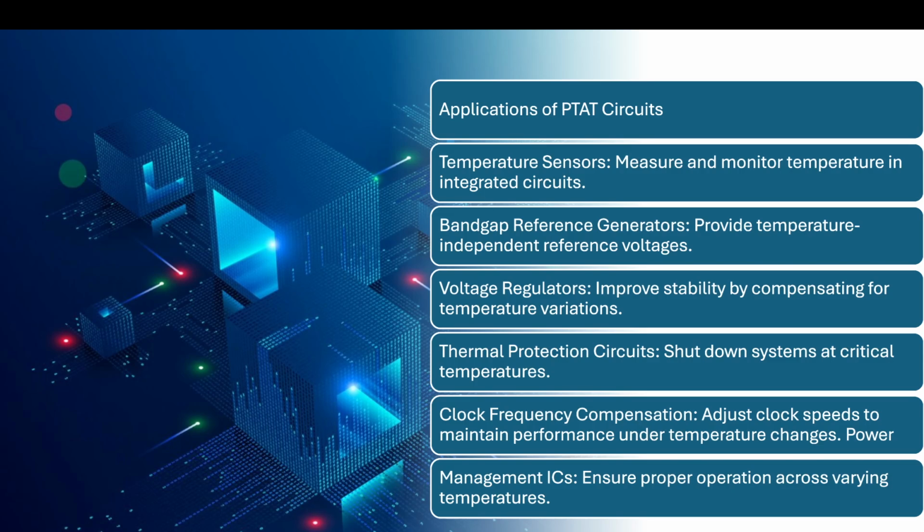These are some applications, and mainly where you design a chip, in most parts of your chip area you can provide this circuit and check whether your temperature is too high or not. It detects the temperature on a particular chip area. If the temperature increases more than its sustainable rate, otherwise your chip will be damaged. So that's the reason this circuit is used in chips.